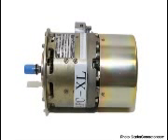The voltage generated by the basic DC generator in Figure 9.7 varies from 0 to its maximum value twice for each revolution of the loop. This variation of DC voltage is called ripple, and may be reduced by using more loops, or coils, as shown in Figure 9.8.